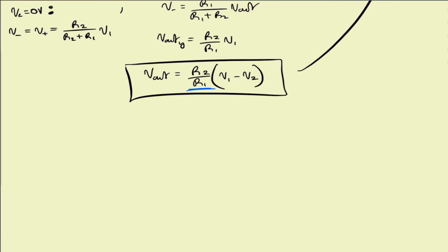So if I pick R2 to be 750 kiloohms, I then get R1, which I should probably just write that. So the voltage gain is equal to R2 over R1. So then R1 is going to equal 15 kiloohms.